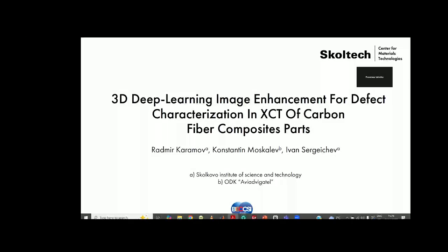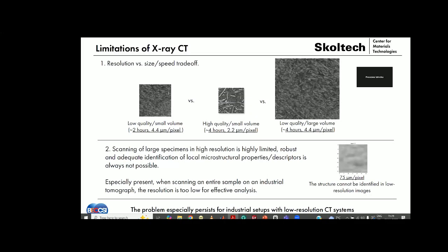Multiplying image enhancement for the defect characterization in XCT of carbon fiber composite parts. So, as Professor Lomov already said, CT can be used for defect characterization, for finite element modeling, for a lot of purposes. But there is a limitation.